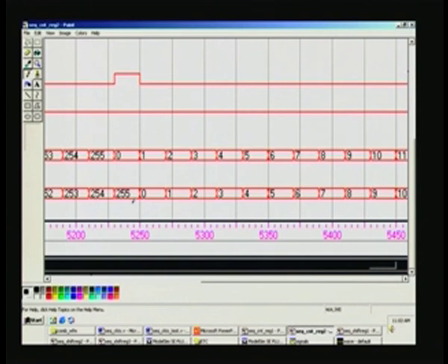It has counted 256 rather totally. So many clock pulses it has gone through. So, you can find out how much it is here around this, right. But we started not on 0, but after a time lag. I think 20 nanosecond we did, 20 into 2 to the power 8, plus some extra time because reset was applied and so on. You can always go and verify this.